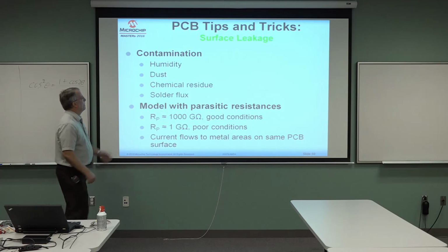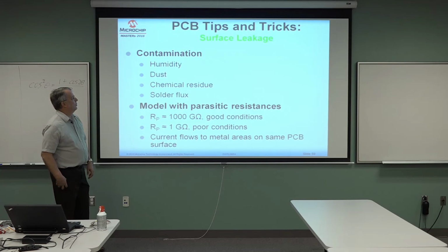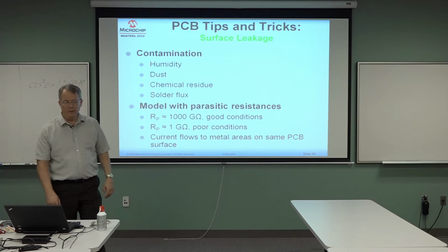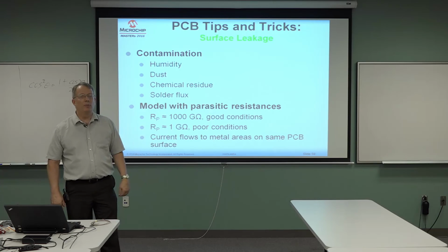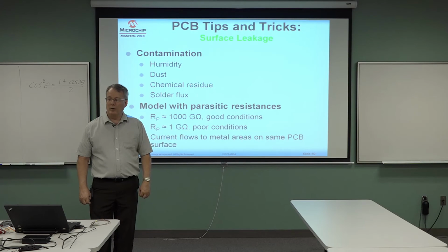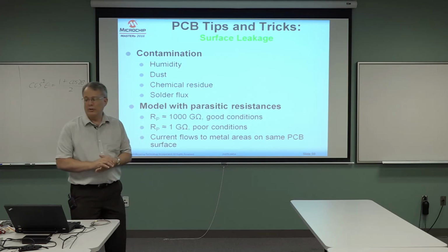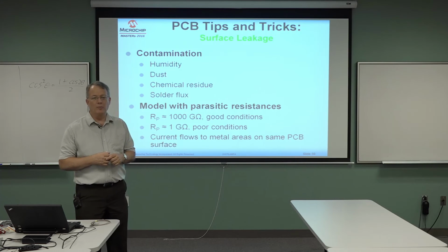Chemical residues. In manufacturing, we get residues, solder flux, all kinds of other chemicals. And so we're all familiar with flux removers. I'm here to tell you that the standard flux removers can also be a problem. They'll take the flux off the board, but they will leave a residue that at the precision levels we're talking about is a real problem. That was another contributor to our errors when we're measuring our op amps.